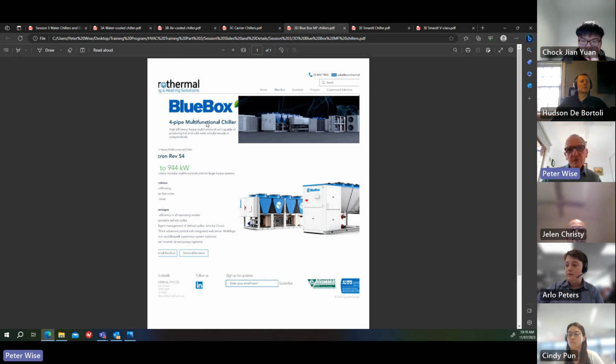Clima Veneta is another one, which Mitsubishi own now. So there's quite a few options there. Just be careful with these that you read the technical data, because from my recollection, on both the chilled water and heating water sides, you need buffer tanks, and quite large buffer tanks. So just be aware of that. Don't design a system without that.